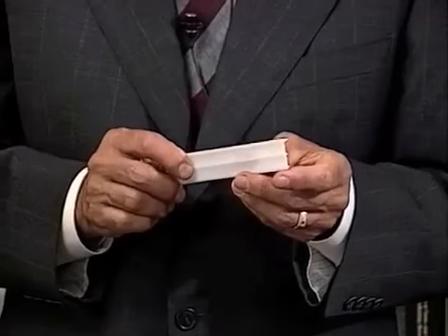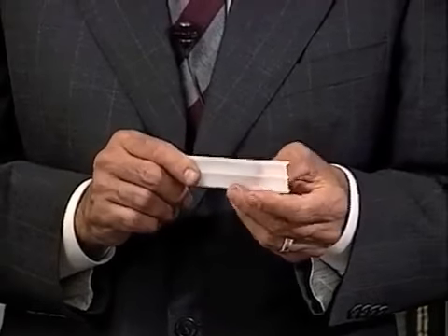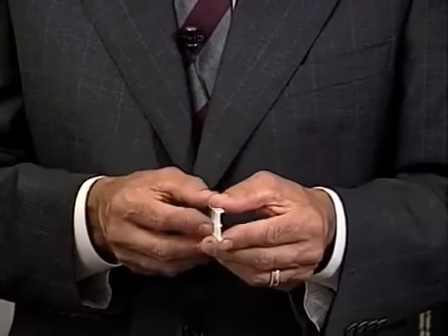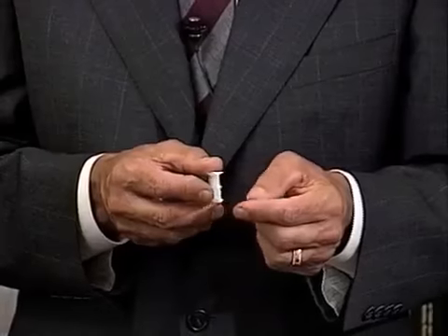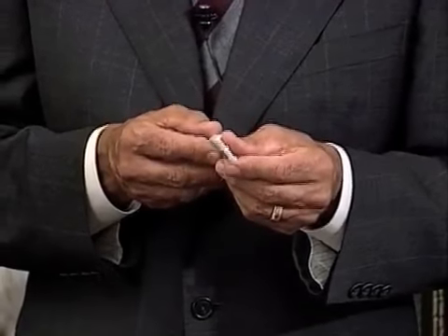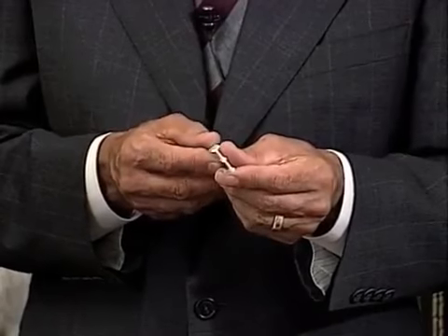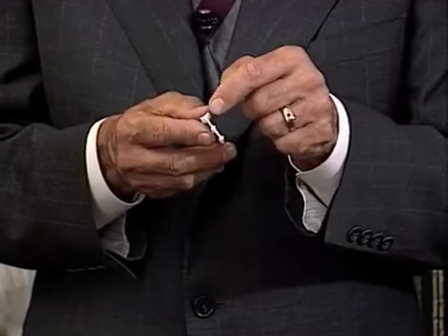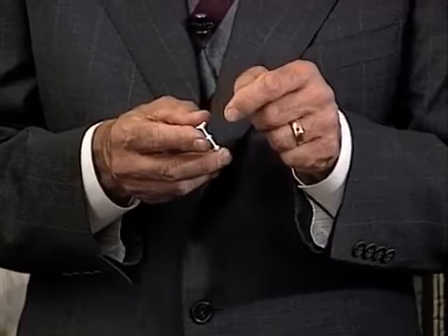The disadvantages are that the material is rather flimsy, so it's difficult to install them in straight lines. Also, there are times where it's difficult to push the insert into the concrete because aggregate particles don't move away. So the insert gets kicked to its side, and the concrete can start breaking away from wheel loads or traffic right here in this top narrow area.